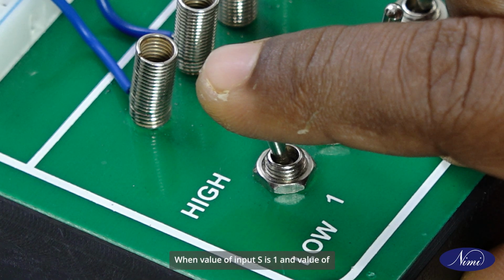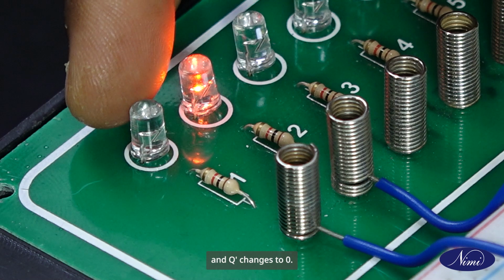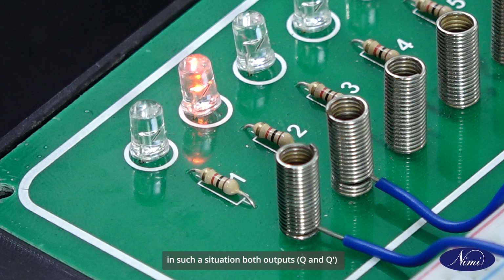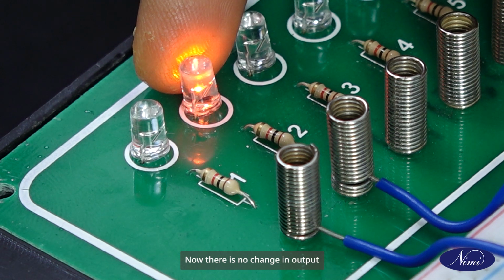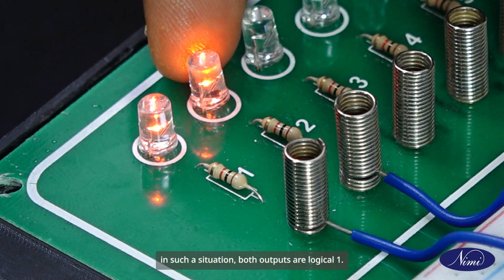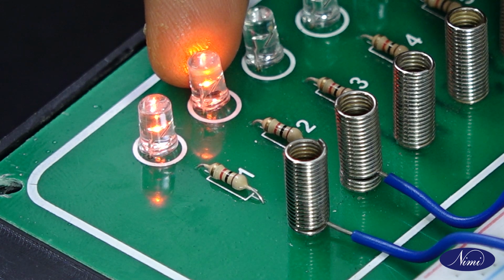When value of input S is 1 and value of input R is 0, output Q becomes 1 and Q bar changes to 0. Such a state of flip-flop is called set condition. When both inputs S and R are 0, in such a situation both outputs Q and Q bar remain in their previous state. Now there is no change in the output. When S and R both inputs are 1, in such a situation both outputs are logical 1. This state is known as forbidden state.